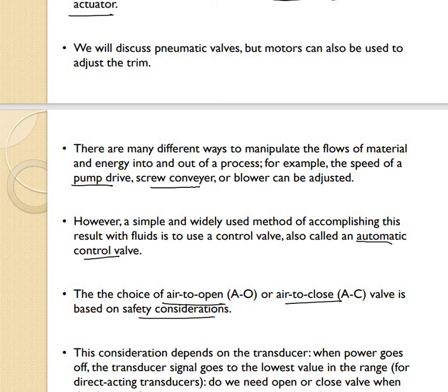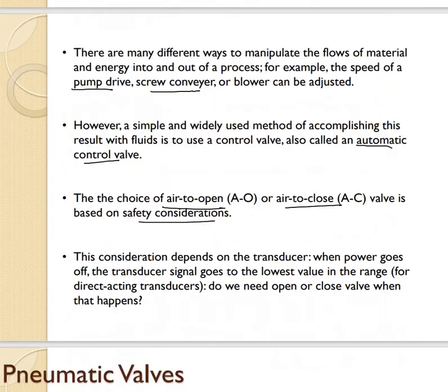This consideration depends on the transducer. So when the power goes off, the transducer signal goes to the lowest value in the range for the direct acting transducer. So logically, do we need an open or close valve when this situation happens? I will explain this in detail.